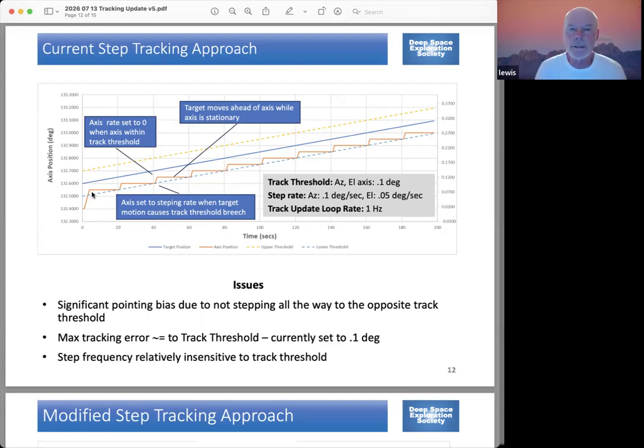There's one aspect of this problem that we haven't really addressed here, and that's what is the bias in the encoders? That's what we run calibrations for. And to really nail that number, you need to run the calibration with the feed that you're going to use. We've never run that calibration with the S band or the 8 gigahertz. We've only run it on the 1296 and the 1420 feeds.